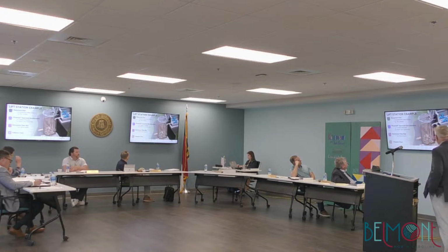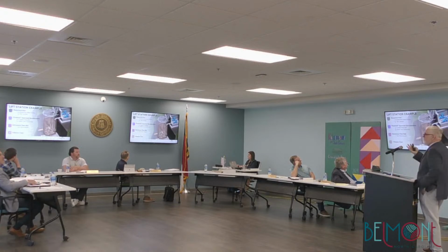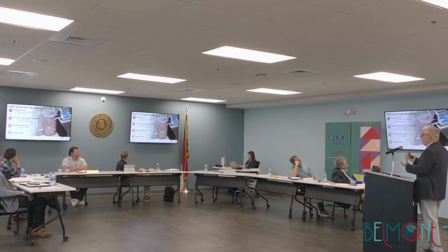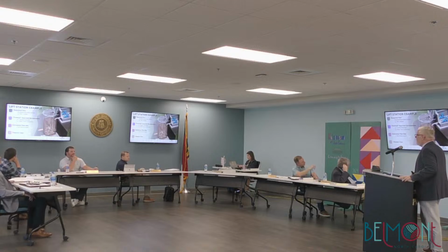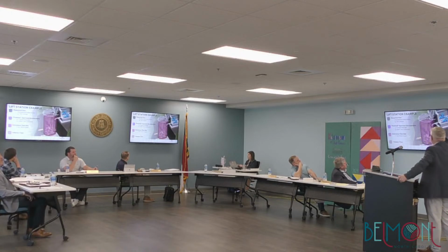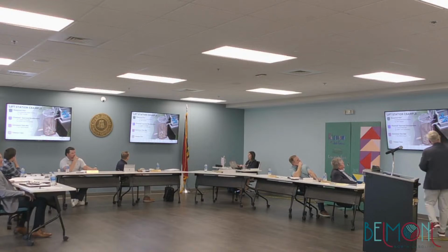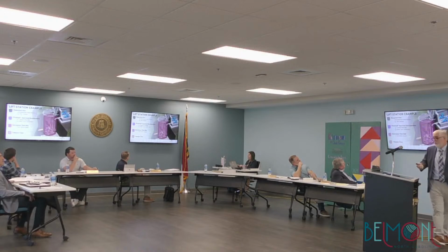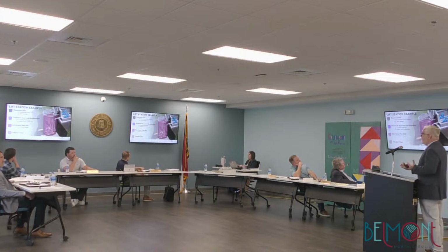But I look at tributary flow. This is that bluebird day, right? This is a day like today. It's not rained. System's working great, Public Works is happy because they're not having to respond to emergencies or having SSOs, that kind of thing. Then I look at extraneous flow. And extraneous flow, if you can see here, is eating up that much capacity, because you really need to account for that potential flow, just like you account for promised flow for a future development. It's part of the system.